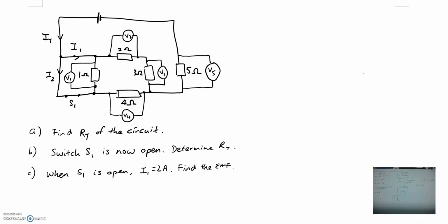So over here you realize that at a certain point, as the current flows from this point in the circuit up to this point, there's actually a split. But what you notice is this: the I2 path over here has actually no resistance, whereas for the other path, you notice there's all the resistance over here. So what eventually happens is this. There's actually a short circuit going on, and only the one in green will have current flowing through it. Okay, so all those in blue will actually be short circuited.